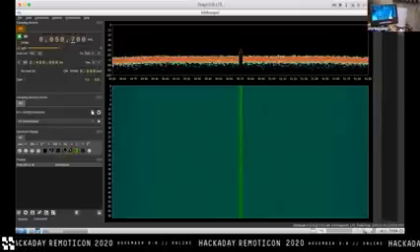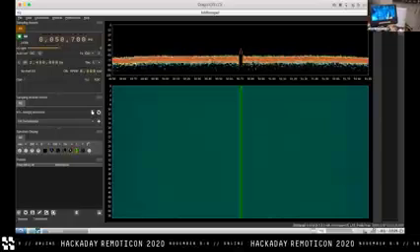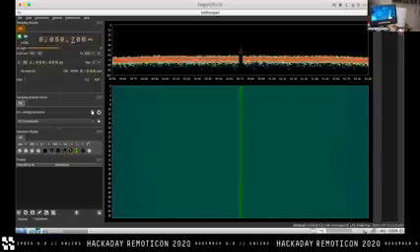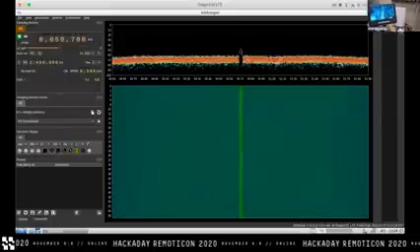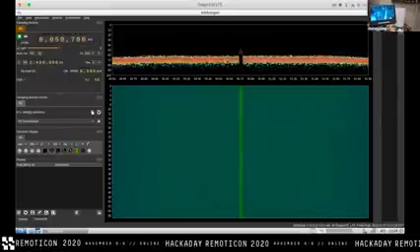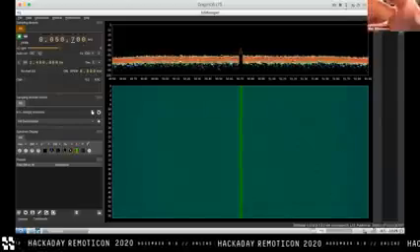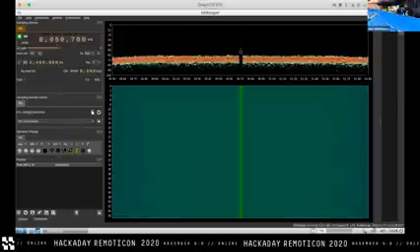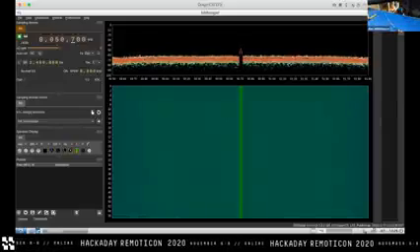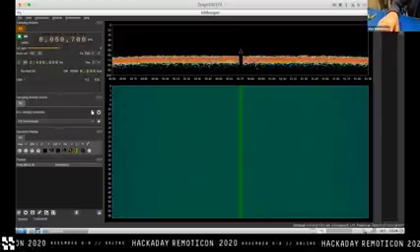So it makes perfect sense that we didn't actually see much up here when I was trying to test each of these individual traces, and we did see a bunch down here. I never even got over to the proper place to measure, which would have been this trace running down there on the top side of the FPGA. Just for giggles, let's go back and see what that has to say about things, because we should be able to see exactly which pin is sourcing all of that current.